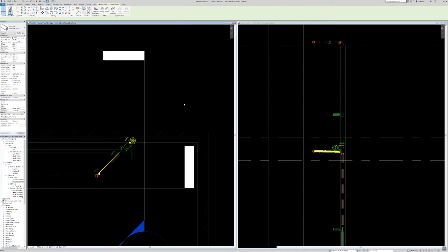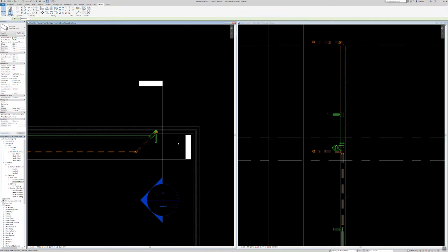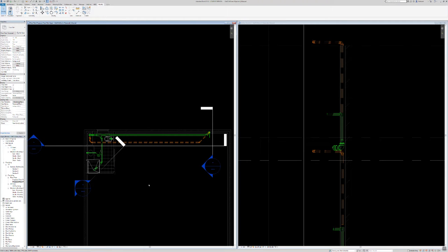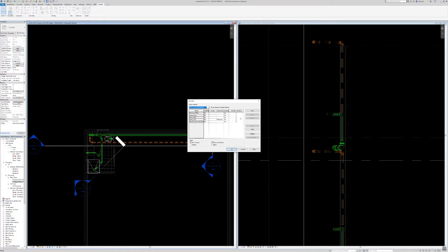Now to beat this, there are two ways we can do it. We can set them as I draw my hydraulics. I tend to set up my templates and work sets. So just to go through and show you, I have an even, an odd, and a vertical. The reason I have the vertical is because I believe all stacks should be verticals, so they're shown on every plan.